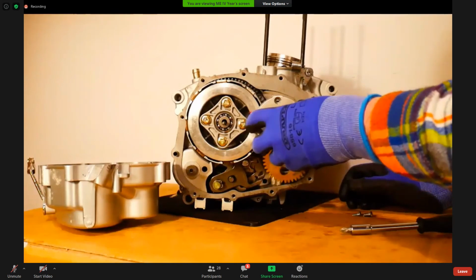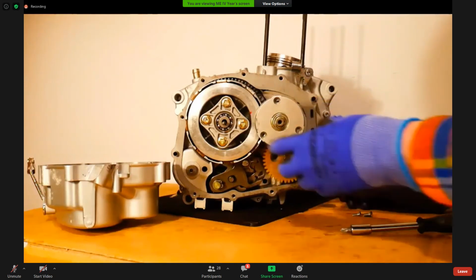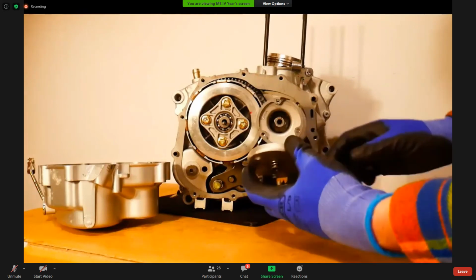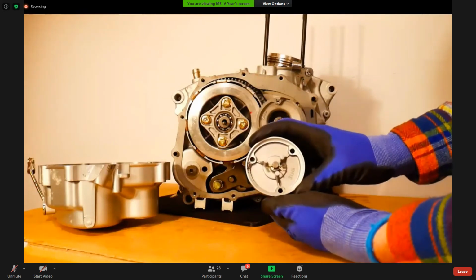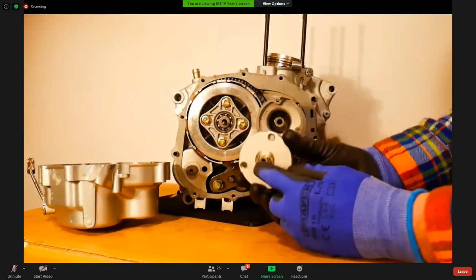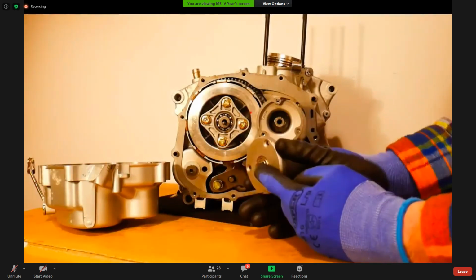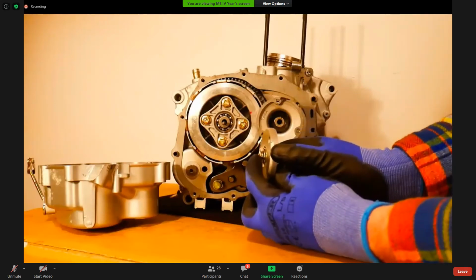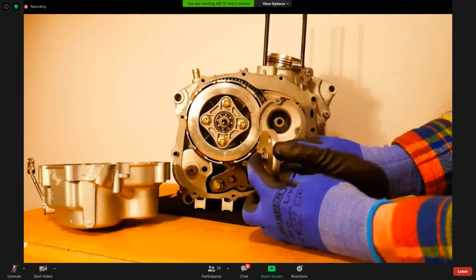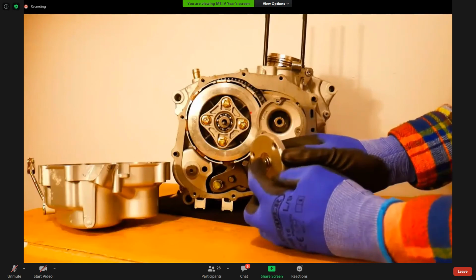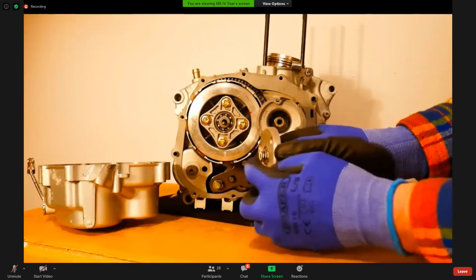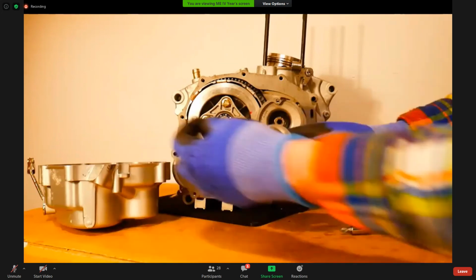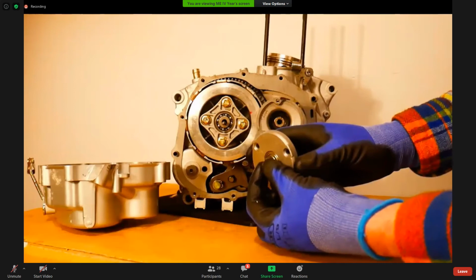Okay, so with the screws loose, I can just take the cap off the centrifugal oil filter. Okay, so in the cap, we can see the little valve. The valve is on a spring, so that's just side view. So the valve is on a spring, and you can see that it moves in and out. Okay, so the spring wants to push it out this way, but when you put the clutch cover on, the hole on the clutch cover will push on this, so it matches up perfectly.